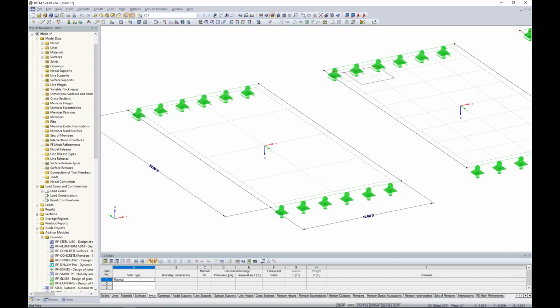So this is going to abide by that global FE mesh of 5 feet. And you'll notice a very coarse mesh. We only have 2 elements across the width. And I can tell you this is definitely not ideal. The only place that we're getting results here within the program after we run the analysis is at every FE mesh point. Definitely not adequate, much too coarse.